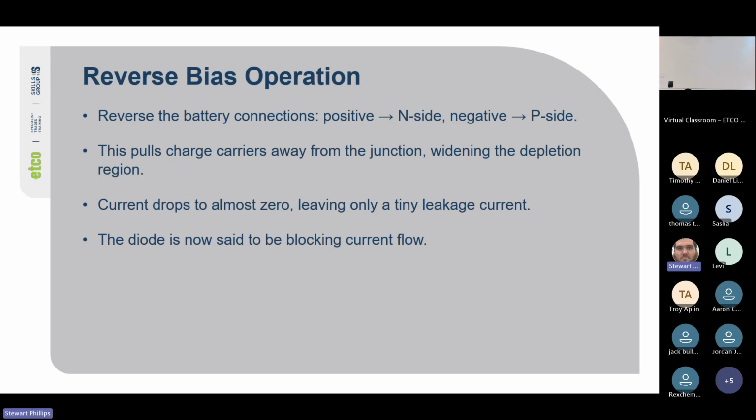So if the reverse voltage becomes too high, though, the electric field can force electrons across. This is what we call breakdown, and can damage the diode unless it's designed to handle it, like a Zener diode. Basically, a Zener diode is designed to work in negative bias in order to keep voltage levels to a set voltage. So if your Zener diode is set to have a breakover at 24 volts, as soon as we get above 24 volts, it'll allow current to go through, just to maintain voltage to a set level on the other side, which may be flowing to the load.